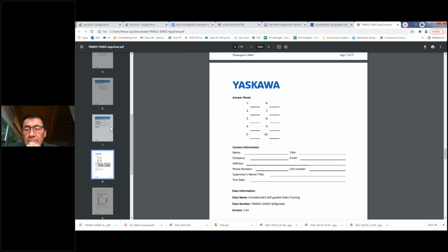And the whole reason DriveWorks EZ was used is because they wanted to do a set number of iterations. So via the Q parameters, they'd program in how many iterations they wanted to do, 100, 200, 300, and then just using SR switches, it would ramp up, ramp down, stop, reverse, ramp up, ramp down, stop, and it would do it for however many tests they wanted to do. And they would run it for hundreds or thousands of tests every week, just switching out units. It was a test rig.